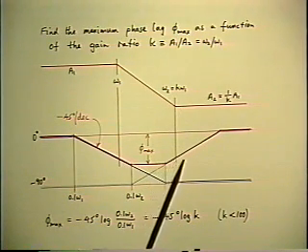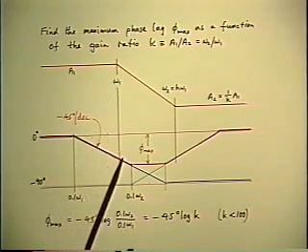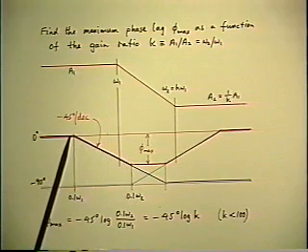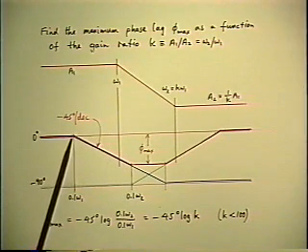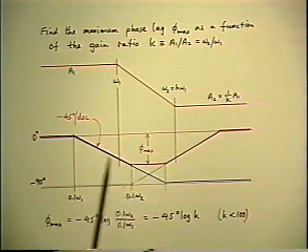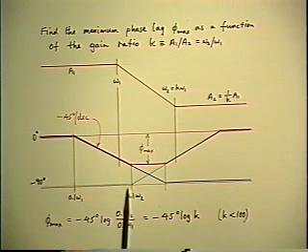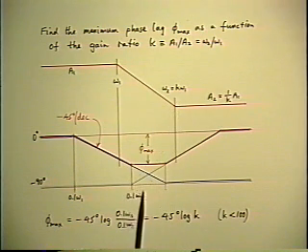That's a very simple little problem because the phase asymptote for the pole remains fixed if the pole remains fixed, and it starts at 1/10 of the pole frequency. And the maximum lag is simply the value of the phase of the pole at the frequency where the overlap begins, which is 1/10 of the zero frequency.